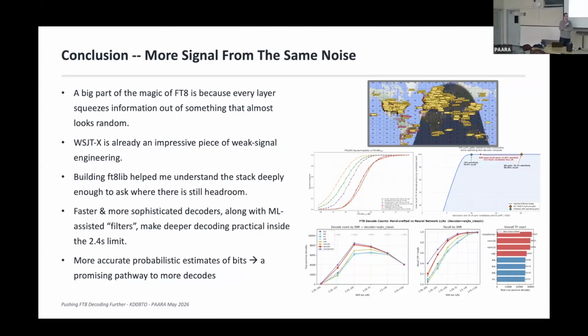That's doable, especially since you can use the really cheap decoders for the strong ones. You can also do the same thing with the LLR formulas: use the fast, easy form, and only come back later and do the more intense one. It's about 100 microseconds, which is about the time it takes to do the LDPC anyway. So it'll add to it for sure, but very good point.